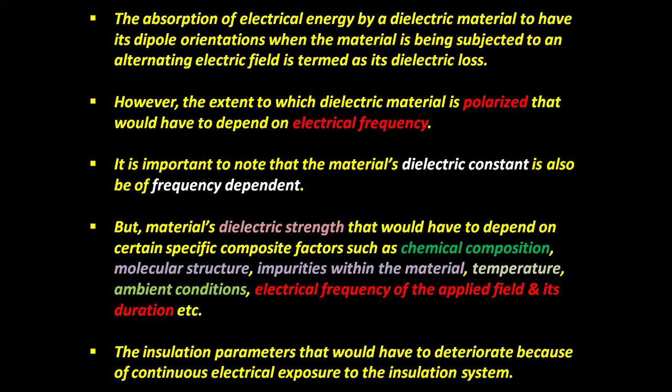The absorption of electrical energy by a dielectric material through its dipole orientations, when the material is subjected to an alternating electric field, is termed its dielectric loss. However, the extent to which a dielectric material is polarized depends on electrical frequency. It is important to note that the material's dielectric constant is also frequency dependent.